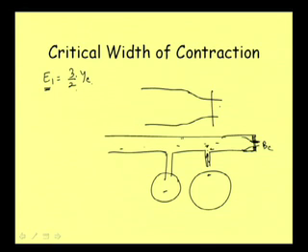Here we are having critical flow condition because our bed width is Bc, and at the upstream we are not having critical flow condition, but we are assuming that the energy at upstream is E1, the depth is Y1 and the energy level is E1, and the energy at this level is the same, because from our diagram itself we are considering that energy loss is not significant. So, we can write E1 is equal to 3/2 of Yc.